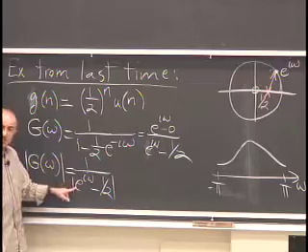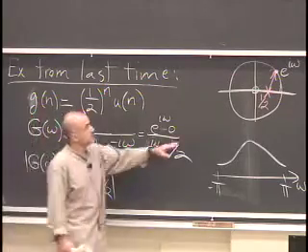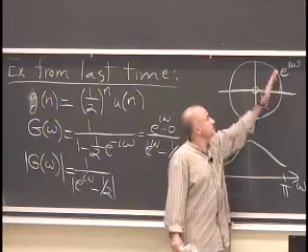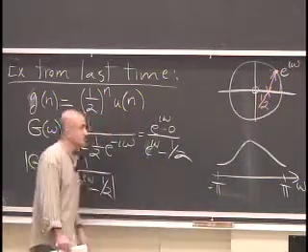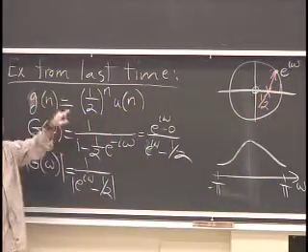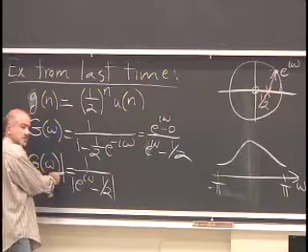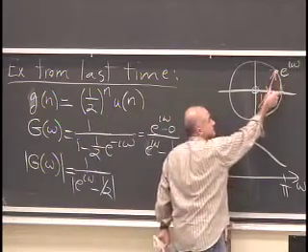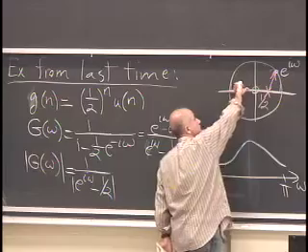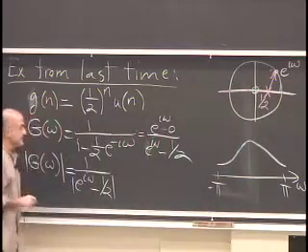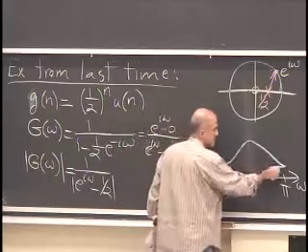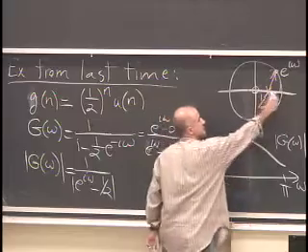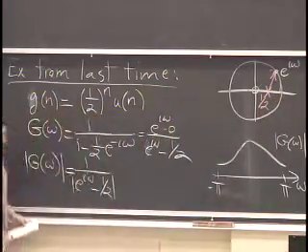So the vector that does matter is this one in the denominator. E to the I omega is where I am on the complex plane. 1/2 is where I've drawn the x. And e to the I omega minus 1/2 is that red vector. You've seen this before. And as we go around the unit circle, the magnitude response changes according to the inverse of the length of this red vector. So the red vector is shortest when I'm at 0. It's longest when I'm at pi, or minus pi. And that's why the magnitude response is the smallest when I'm at those high frequencies, and it's the maximum when I'm at 0.